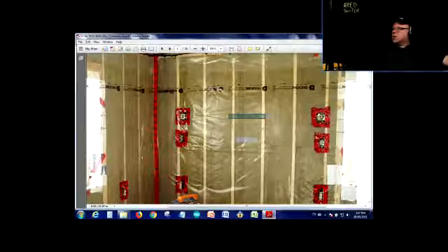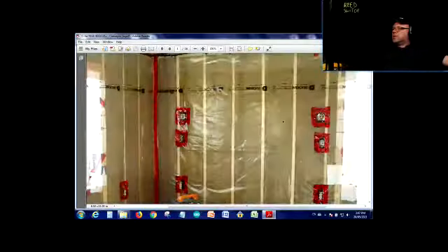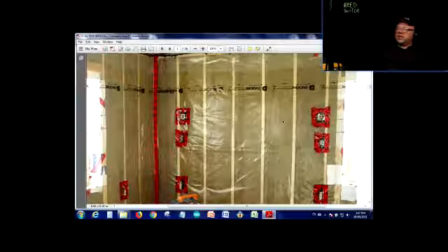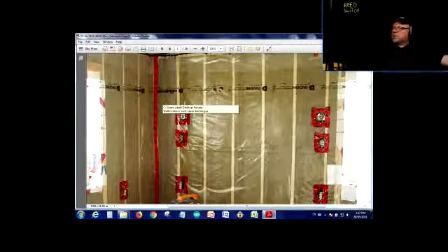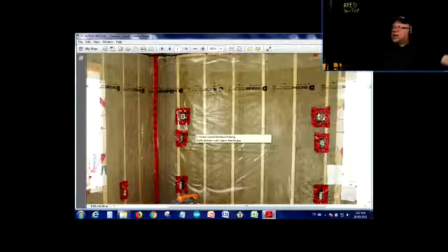Bonus. If you're involved in some sort of construction, it's a good idea to take a lot of pictures before the drywall goes on for future reference, and keep them somewhere that you can find them later. Right? That's the key too. So you're going to see something like that, and you're going to see the foil, the moisture barrier, just put from top to bottom, and it's stuck to the wooden studs, quite often stapled to the wooden studs and whatnot. And you're going to see that red tape.